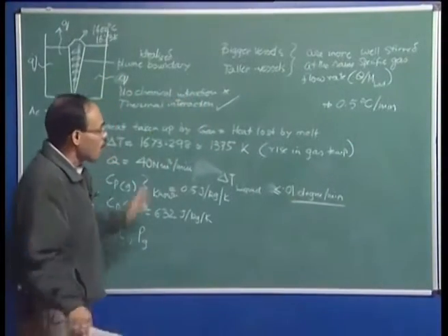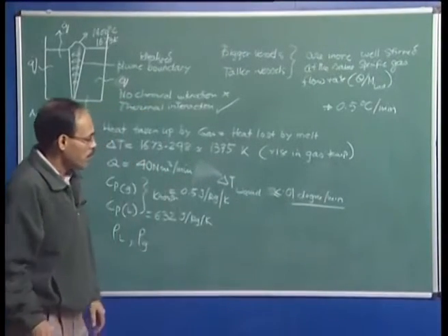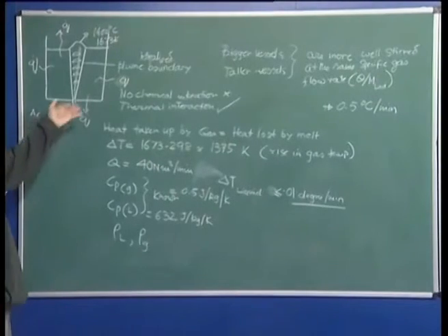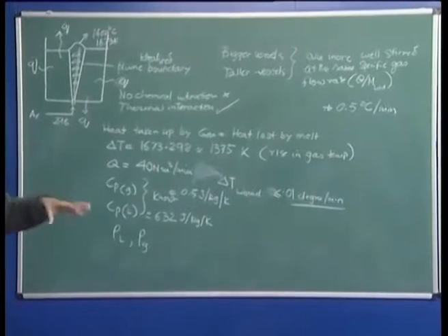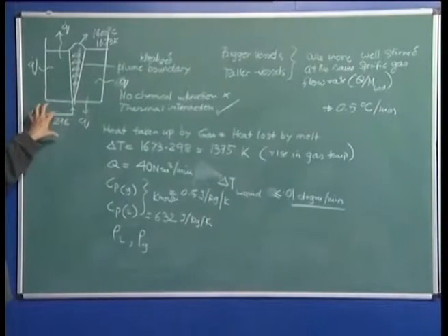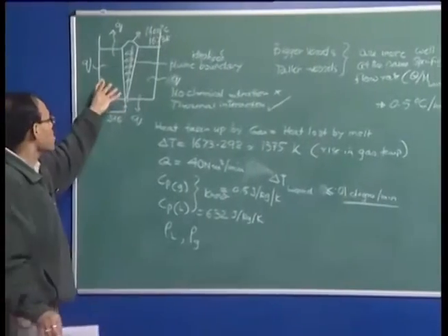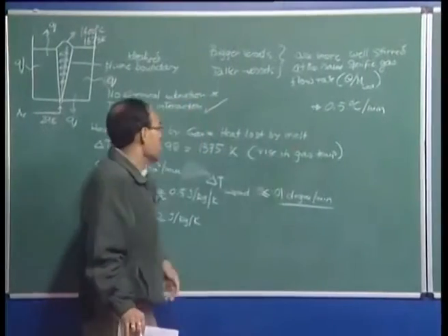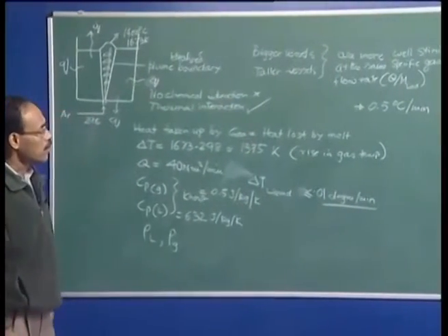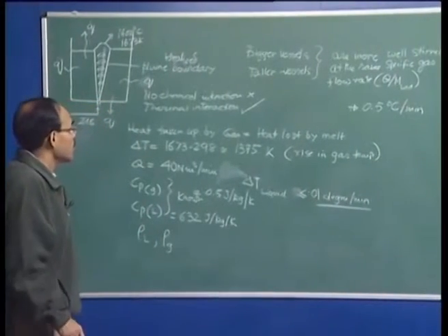to the surroundings. On the other hand, in that particular time, we may have 0.3 degree drop because of the heat which is consumed by the rising gas. So therefore, we can conclude that the injected gas, even though it is cold and is heated up to about 1400 degrees centigrade, due to its low density and low flow rate, the loss of heat from the melt is going to be insignificant in comparison to the loss because of heat going out of the system to the surroundings through the free surface as well as the wall.